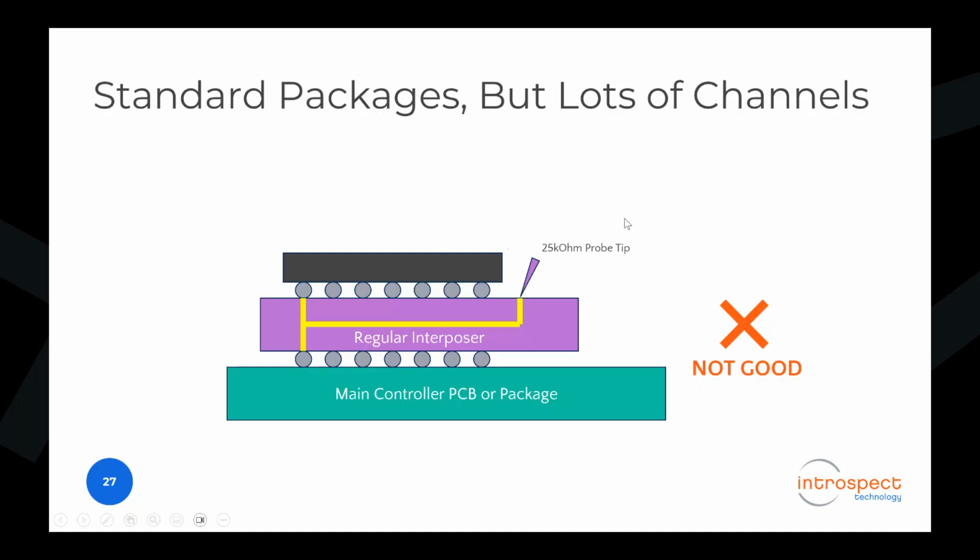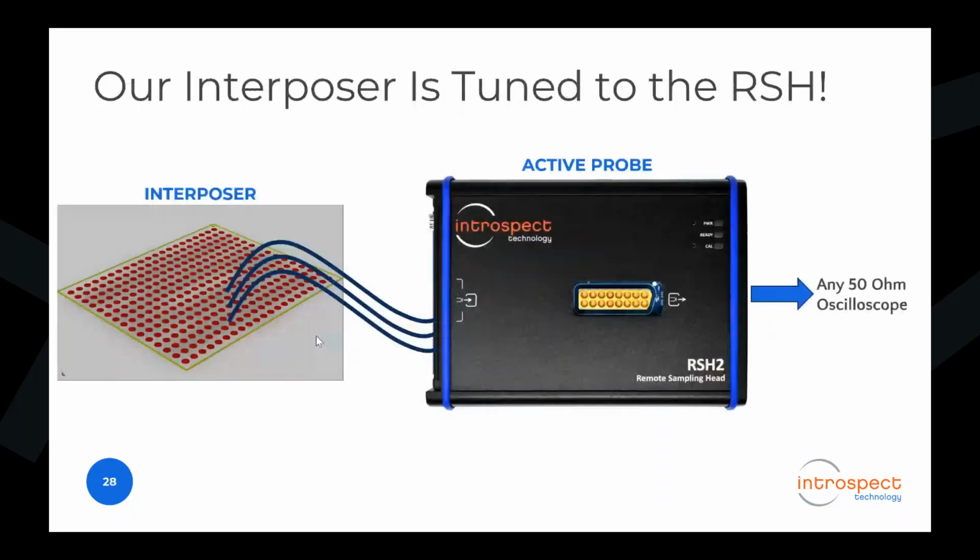And to add jeopardy to this, the active probe is itself high impedance. And as I will describe later, a lot of the LPDDR applications are now running in unterminated mode. So when you have a long stub followed by a high impedance probe, and your memory is running in unterminated mode, that's just a recipe for completely closed eyes, essentially, at the speeds that we are looking at.